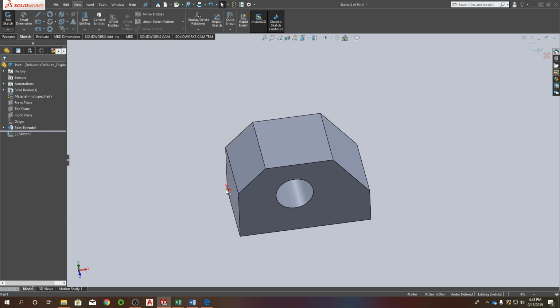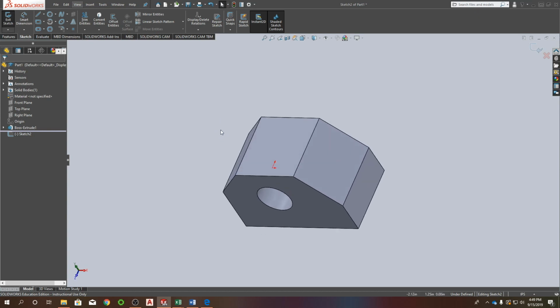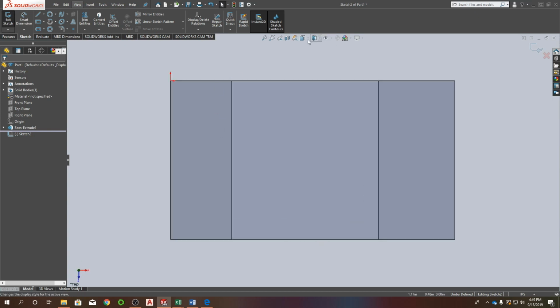I'm currently in the sketch. You can see the little origin point there, and then these two buttons here designate that I'm also in the sketch. Also, we're on the sketch tab, and you can see exit sketches right there. So I'm going to do Control 8 to go normal to, or if you want, come up here and click on normal to.